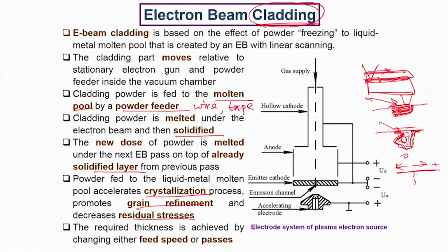So, one needs to find out how you can reduce the relative degree of residual tensile stress on the surface, or if possible bring in residual compressive stress on the surface by way of some special treatment.